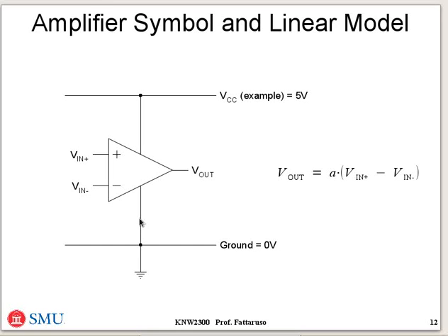And the behavior of the circuit for our purposes can be modeled pretty simply by this linear relationship given here, where the output voltage is simply a large gain factor multiplied by the difference of the input voltages applied to what's called the non-inverting input and the inverting input.